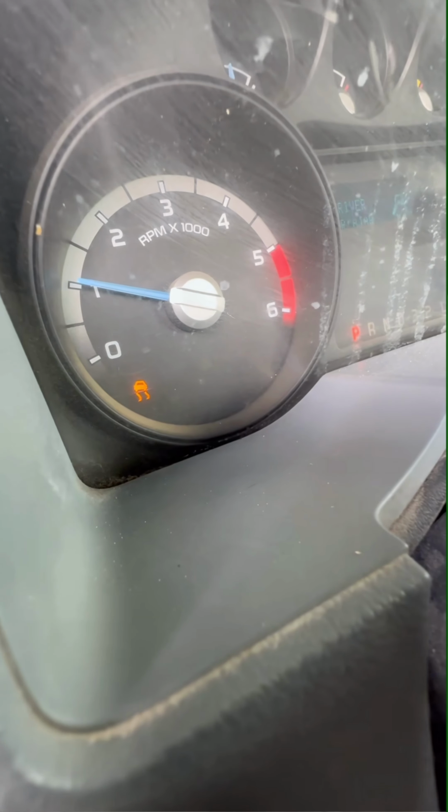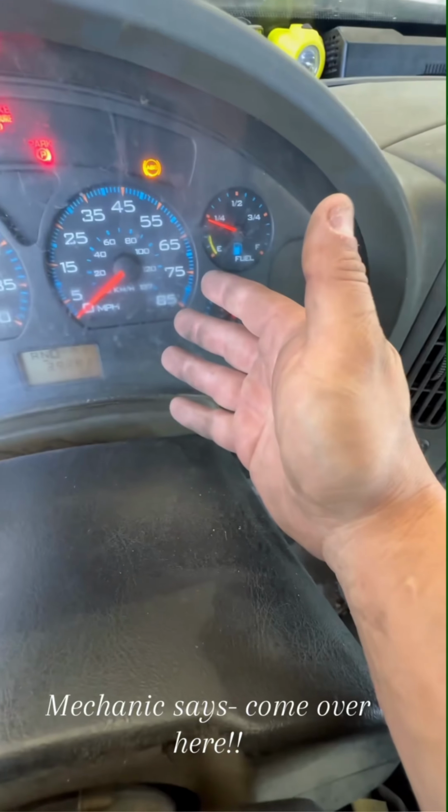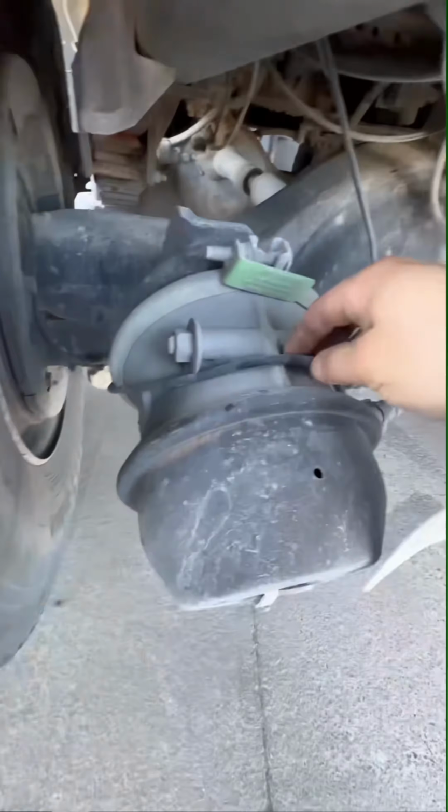Customer states, ever since you replaced my fan clutch, now my ABS light is on. You see, I never had this problem before. Mechanic says to come over here. Let me take a gander. Left rear speed sensor. Wiring looks okay. What about the right rear? No issues here.